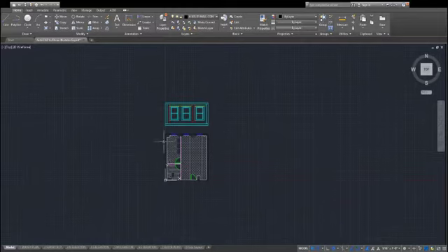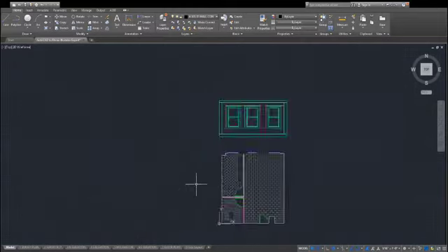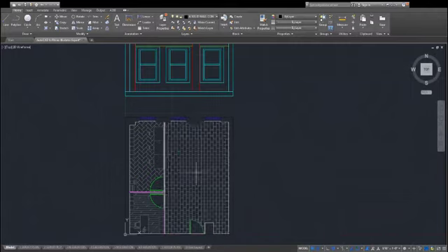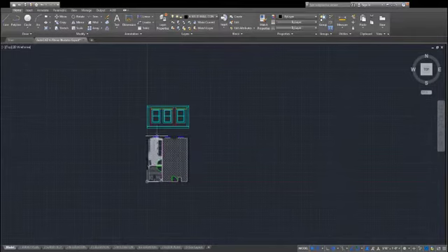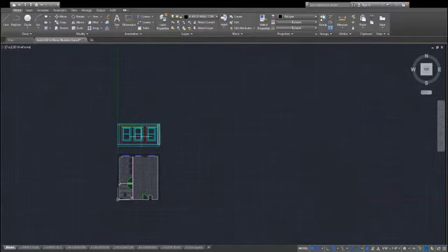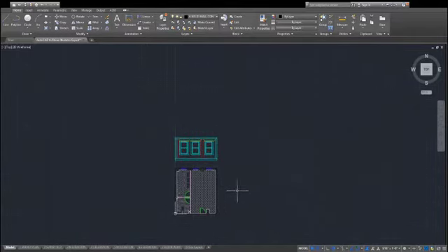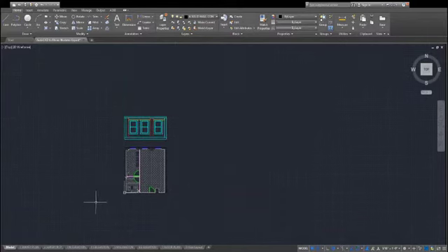So to do that, make sure that only the portion that you're working with in AutoCAD to other programs is in your drawings. If you have any other drawings or reference lines or other stuff that you are not bringing in, make sure you delete those and save a different file version, so you preserve the original version with everything in it and a new version with just the stuff that you're going to export out.